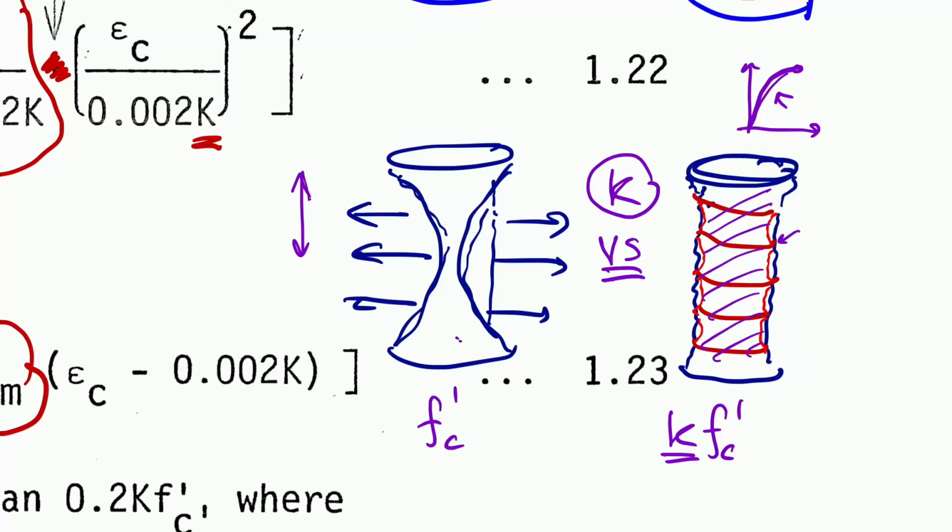But in comparison with the condition after the concrete reaches the peak and then starts the formation of micro cracking, crack propagation inside. Once those cracks occur, which means the tensile cracking, right? Because you have some plane subjected to tensile stress. So that plane cracks, it moves, and when it moves, you get the force in the steel confinement.